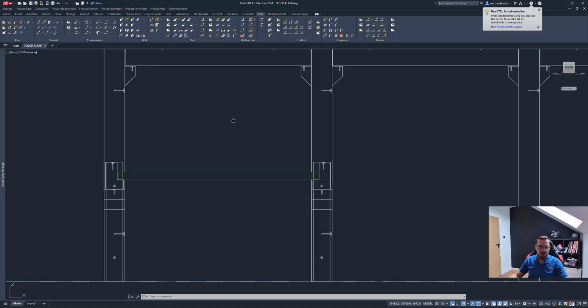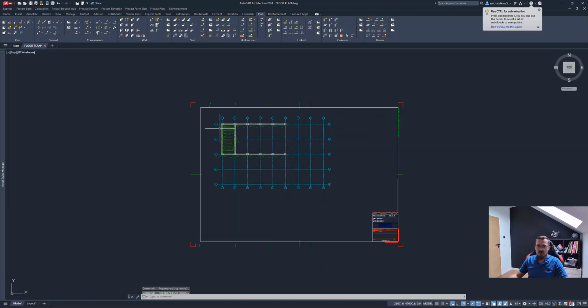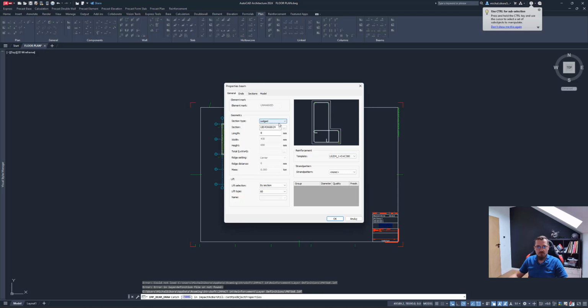And now what we'll be left with is, now I just want to place a couple of pre-stressed columns, as we also have those. Those I want to be tapered columns, and those will be this type. Of course, for this particular element, I don't have reinforcement predefined. I could define that again, going to the definition of the beams and preparing proper shapes to have that reinforcement in this. For now, I'm just going to use it as just a pre-stressed beam.